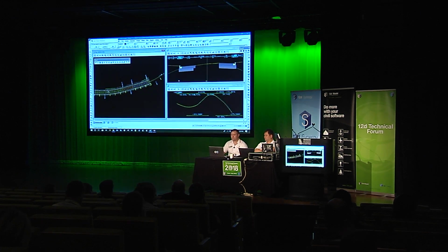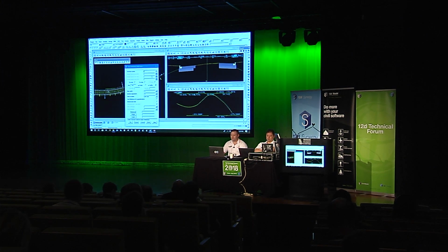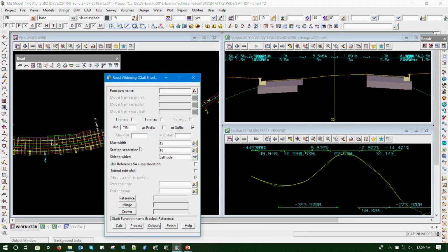All right. So you're all familiar, or most of you will be familiar with the old road widening tool. It's very handy, great for extending existing surfaces, creating those envelopes, maybe create alignments within, that sort of thing. But it is very dated, so things like you can't use smart changes with it. Also the selection criteria is very old school.